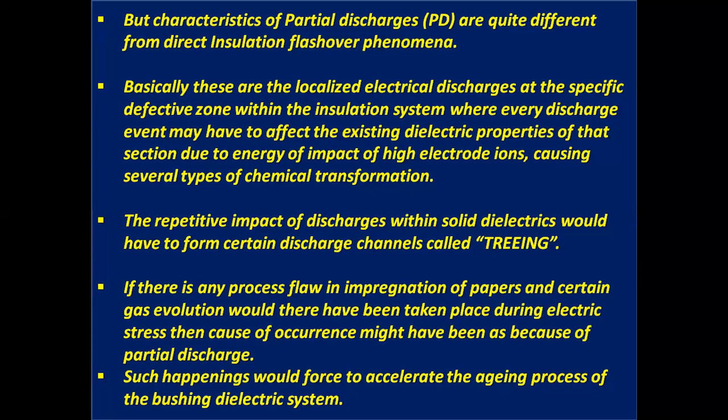If there is any process flaw in the impregnation of papers and certain gas evolution takes place during electric stress, then the cause of occurrence might be partial discharge. Such happenings would accelerate the aging process of the bushing dielectric system.